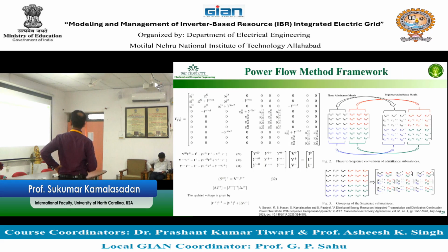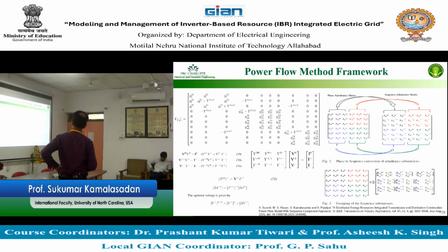So this is how the Y bus will look if you are looking at it in the form of a positive representation. You will also get the negative representation, and you'll get the zero representation, like I said. So this is positive, negative, zero sequence. You can represent this in the sequence form, and then you can write the sequence balance equation: zero, negative, positive.